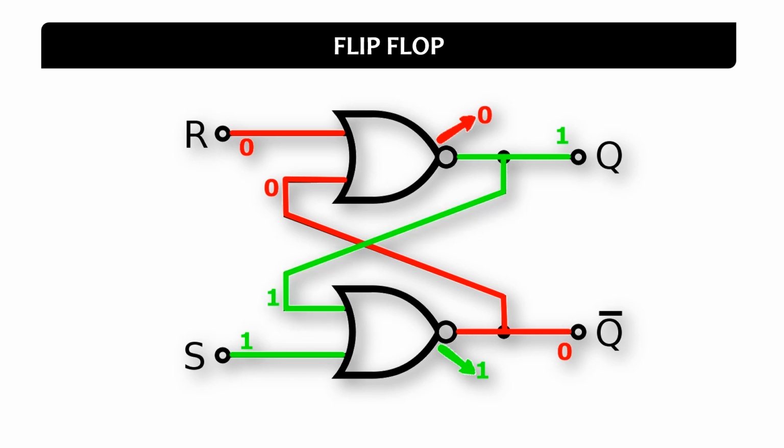So now let's understand what is happening in the image. As you can see, the green line, 1 is my set input, I got 1, but because it's a NOT, I got 0. This 0 becomes the input for the next cycle. Again I got 0, but because it's a NOT, I got 1, and this 1 becomes the input for the next phase or next state.